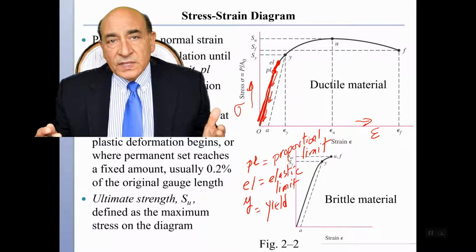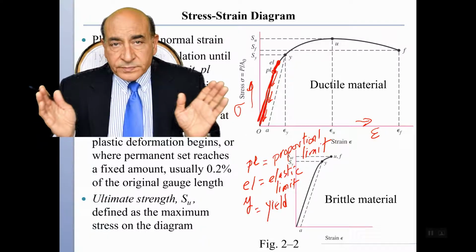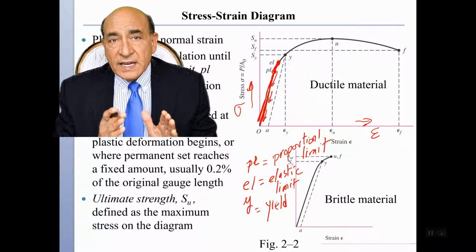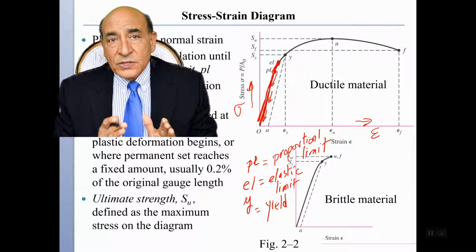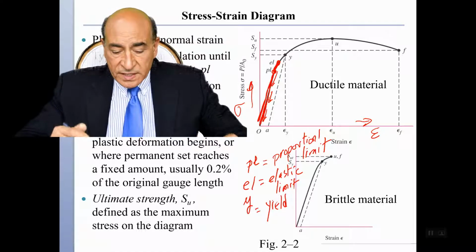I recover only a portion of that. I recover only the elastic part. And then the material goes back to a strain. It will not be strain-free. It will have some amount of permanent deformation that is called residual strain in the material, plastic strain.